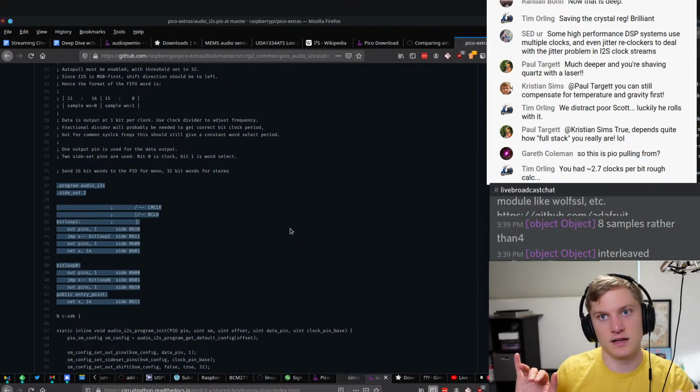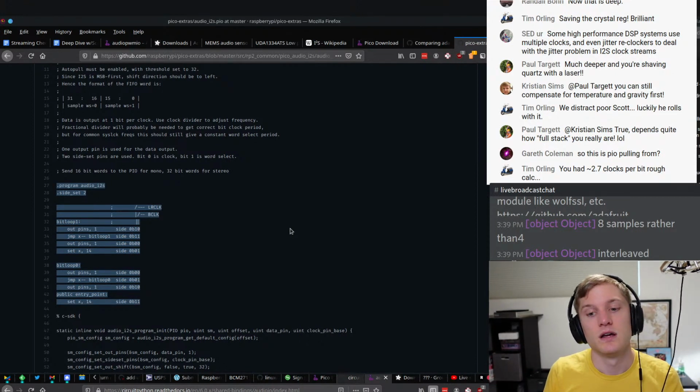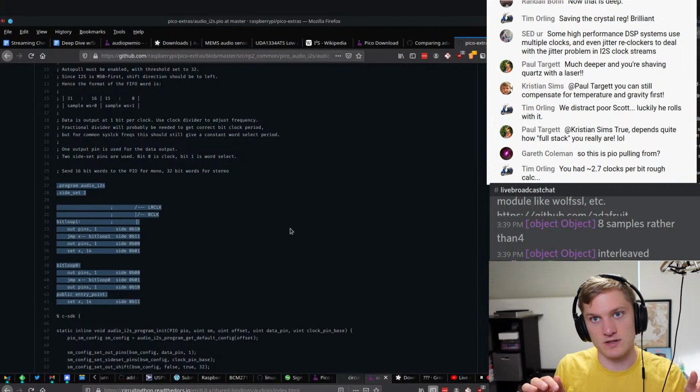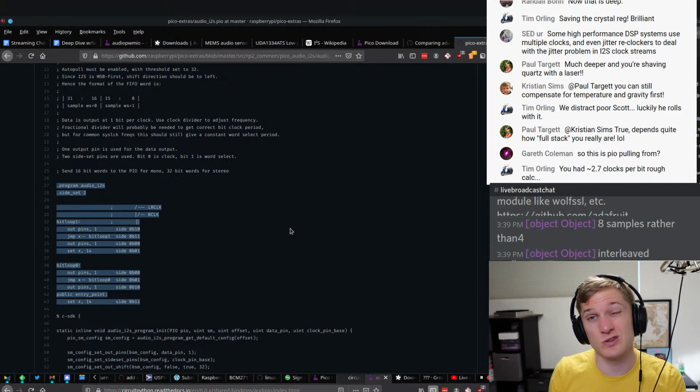The ping pong buffers themselves are not that hard, but the problem is that we have this system where we're getting the sample buffer from something else, like the mixer, and potentially we have to convert the format of the mixer into the format that we're going to actually produce, or we actually need to copy things over, which I think is pretty straightforward for the I2S case, but it's going to be more difficult for the PWM because we're going to do like 10-bit.